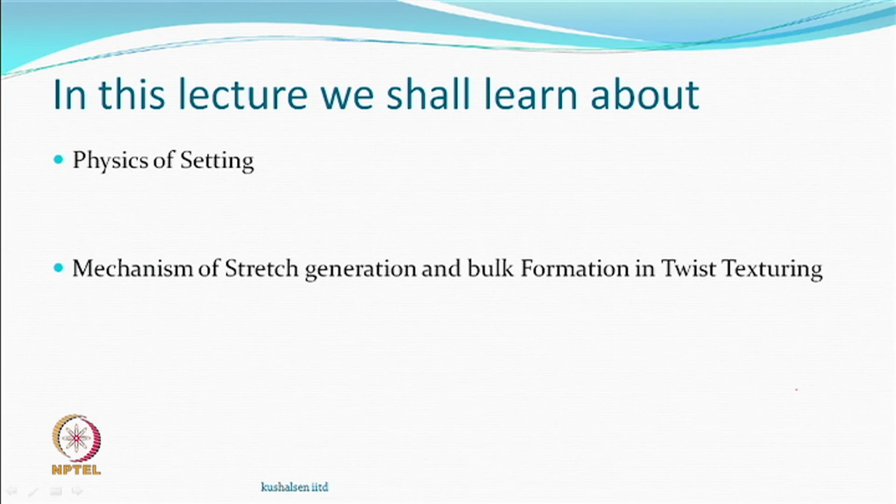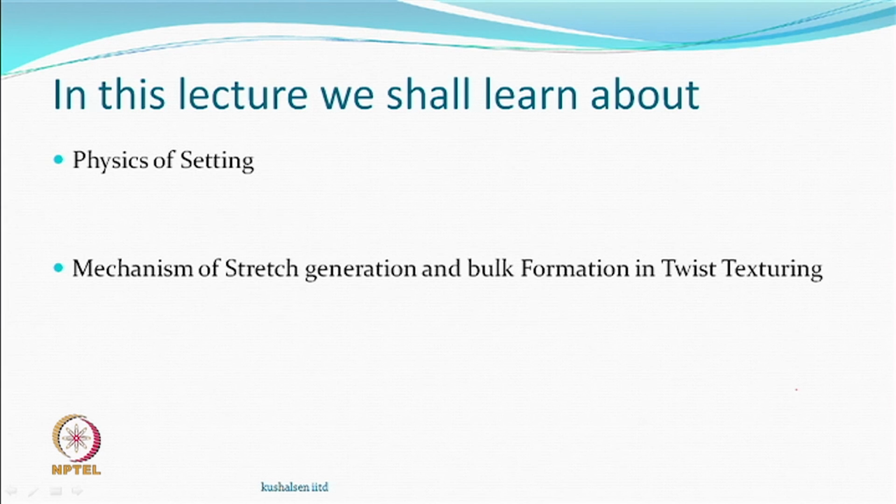In this lecture, we would try to concentrate on the physics of setting and the mechanism of stretch generation and bulk formation in the twist texturing mechanism. It does not matter whether it is duo, turbo duo or false twist or Helenka, this should cover all these types of processes. So, physics of setting, mechanism of stretch generation and bulk formation in twist texturing.